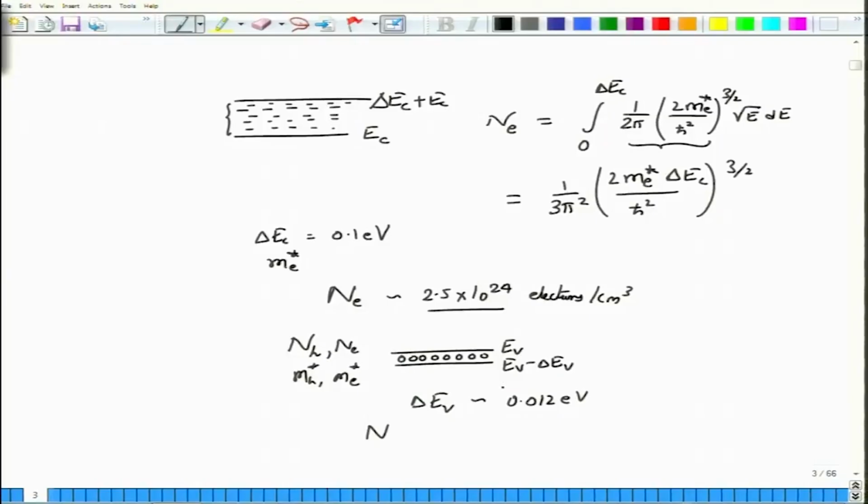Now, we need to look at how much current is required to maintain this amount of carriers. Before we do that, we need to know a little bit about the lifetime of the carrier. What we mean by lifetime is the characteristic time over which electrons can combine with holes and emit a photon. This is of course applicable in the direct band gap cases, as we have emphasized repeatedly. This lifetime is, let us say, tau pH, and the current required to maintain this amount of carriers will be about Ne divided by tau pH, and this is the current density.